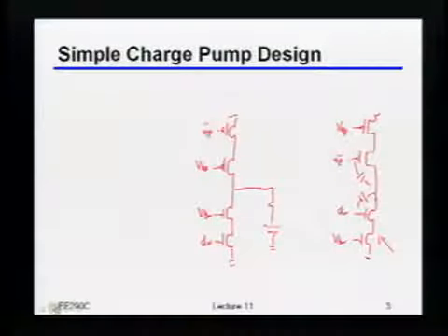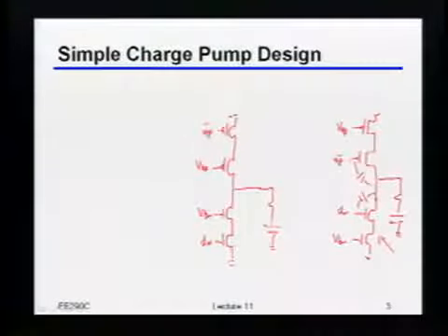And maybe I'll be more clear. Let's say my loop filter is like this. If my loop filter is like that, what is my control voltage referenced to? Yeah, it's referenced to ground, right? Because I put ground on that cap, which is kind of implying that I want everything to be relative to ground, right?